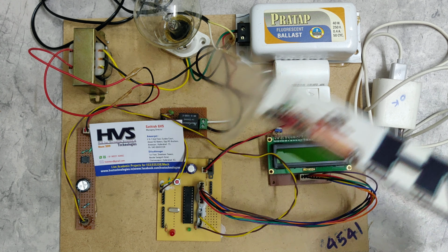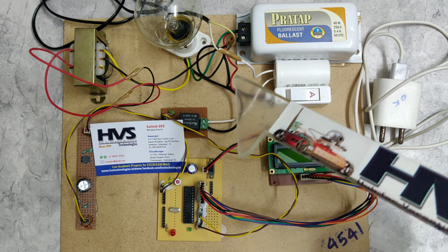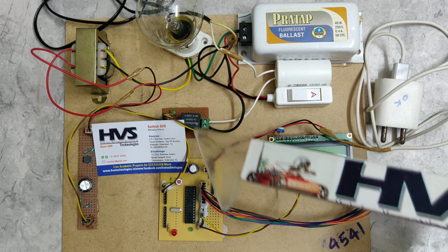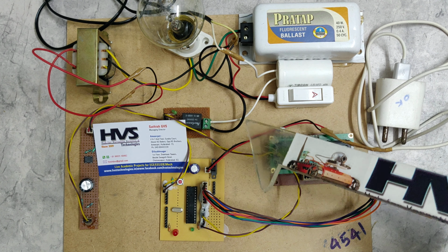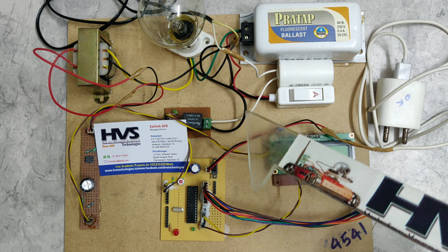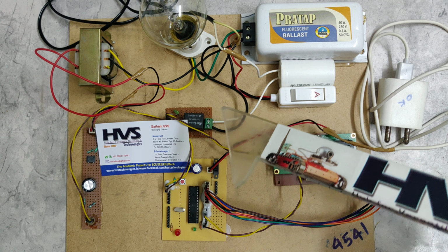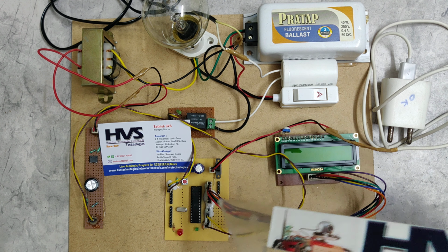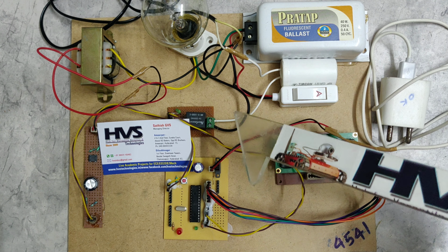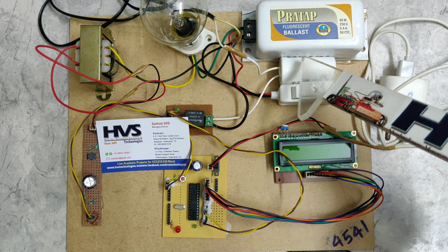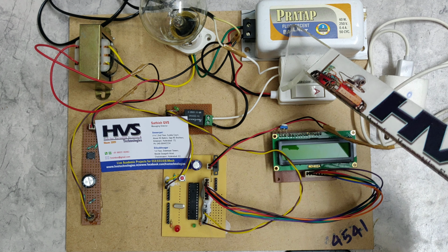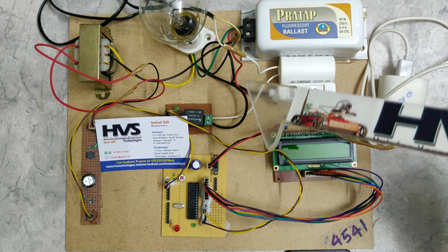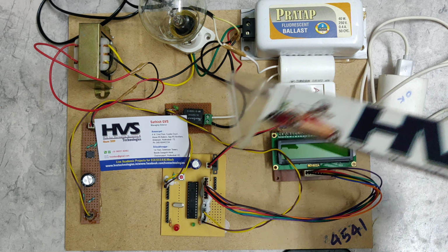So what is the phase angle time difference? If 20 milliseconds is 360 degrees, then x milliseconds is how many degrees? That gives us the angle. If it is 0, then cos 0 is equal to 1. If the difference is more than 0, then cos of that angle is less than 1. That will be identified by our PIC microcontroller, and based on that value we switch on the capacitor, because the capacitor leads the waveform and the inductor lags the current waveform. Then these will be compensated. In this way we correct the power factor in power lines.